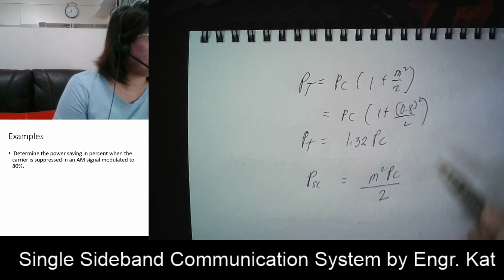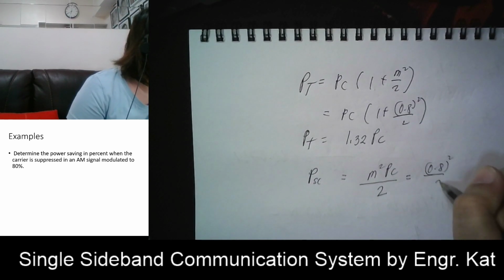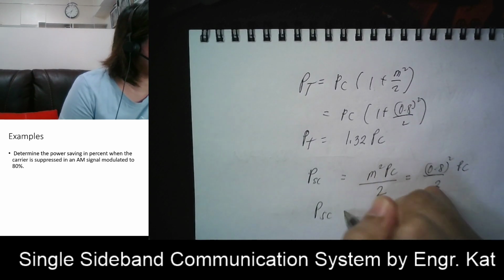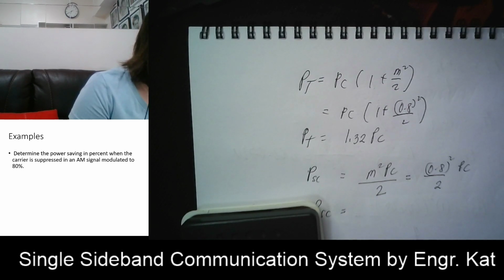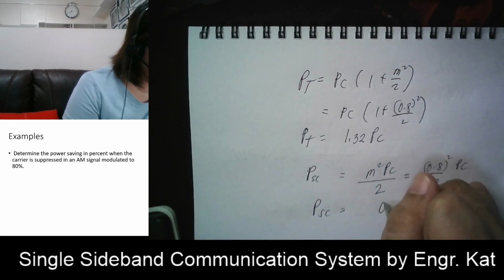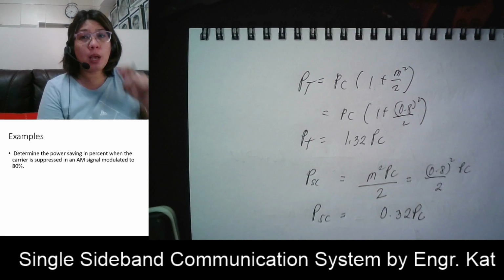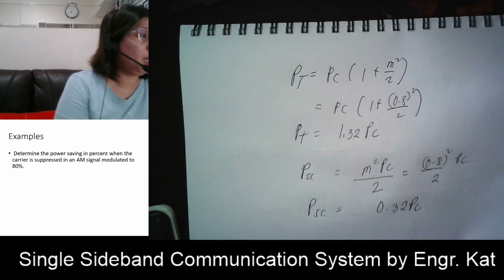Okay, so substituting here, you have 0.8 squared all over 2 multiplied by your PC. So the total transmitted power for a suppressed carrier is equivalent to 0.8 squared divided by 2. So that is equivalent to 0.32 of our carrier power. So how do we solve for the power saving?